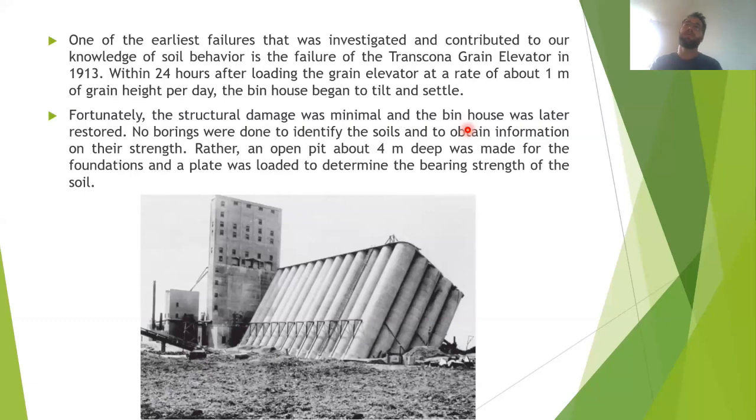And the thing is, there's one thing called a safety factor. Safety factor is how much my ground support can take versus how much it needs to take. So usually for buildings it's 1.5, so you need to maintain 50% more strength than you actually need. For the construction phases, it's 1.3. So you just need to be sure it's not going to collapse during the excavating.